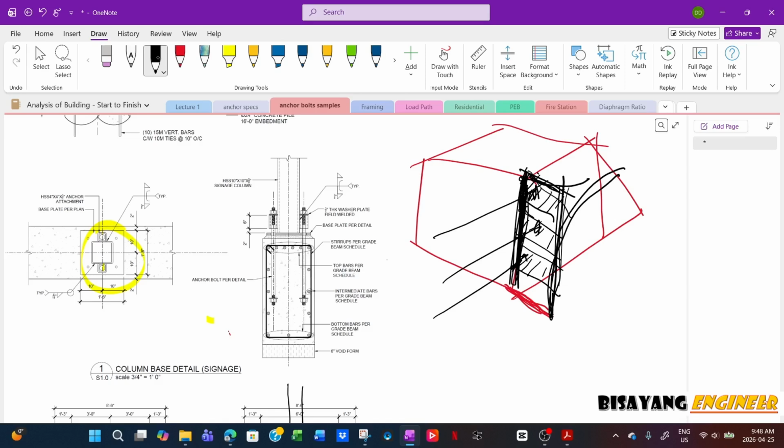So actually these are all structural members trying to hold this one, acting as a cantilever support, and this bracing is rigidly attached to the column here. So instead of relying on the bracing here to handle all the loads as a cantilever, it's just too big if I release the base here.